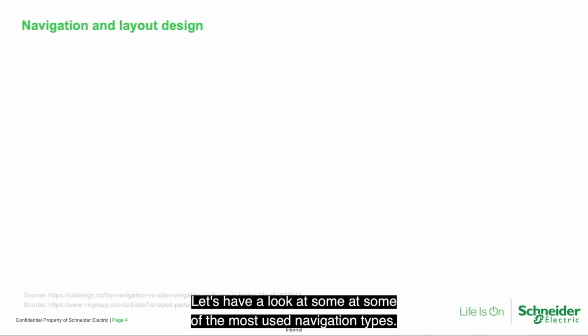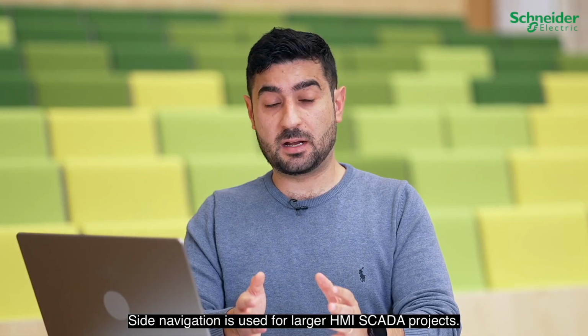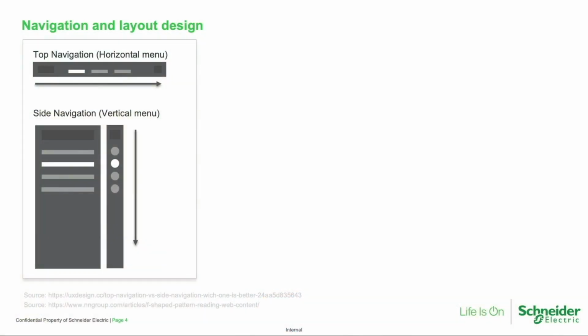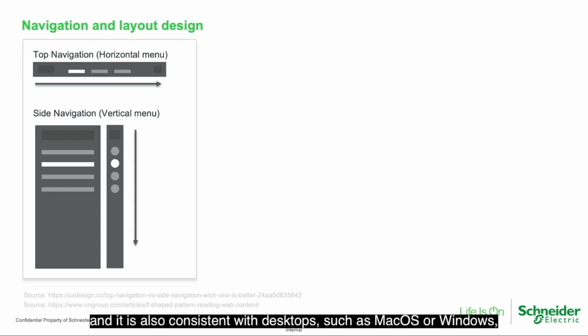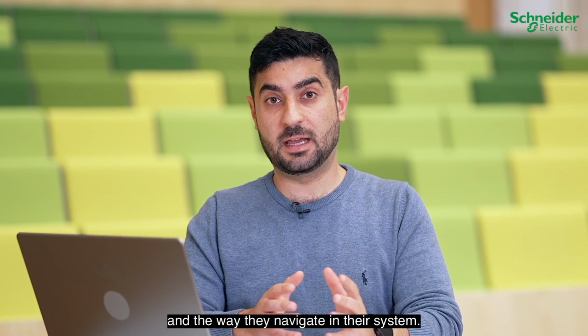Let's have a look at some of the most used navigation types. So, the most used navigation types are top navigation and side navigation. Side navigation is used for larger HMI SCADA projects. It improves scanning and readability speed. It also supports a larger number of buttons or links to navigate throughout your system. And it is also consistent with desktops such as Mac OS or Windows and the way they navigate in their system.